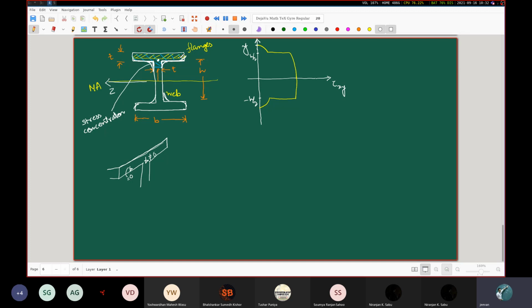Because of the necessity of the flatness of certain structures, it may be required to have this kind of sharp corner that may not be done away with. You can't get away from it, but wherever you can avoid it, you try to make it smooth. So in those regions, the current theory that we have discussed here is not going to hold. But as long as you stick to the middle of the geometry, the tau xy expressions, the formula or the procedure that we have, will be fine.